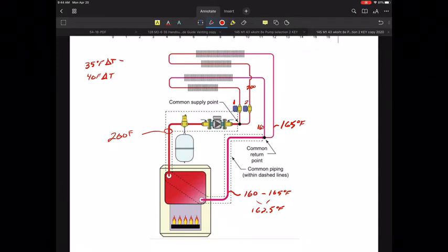All right, now, why would we be low on water flow, or what would be the problem here? If I designed my system assuming that we were going to have this big of a delta T, I would have had to make sure that the heat emitters near the end of my loops, whether it's here or here, were made a little bit longer.